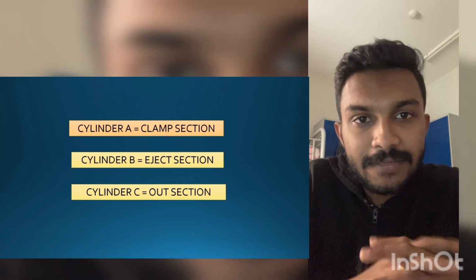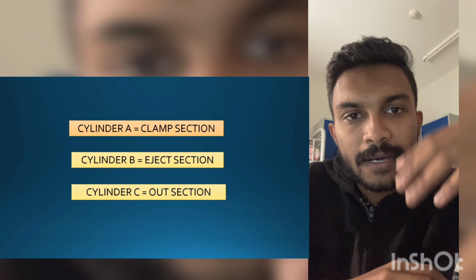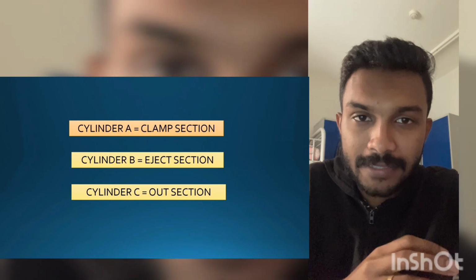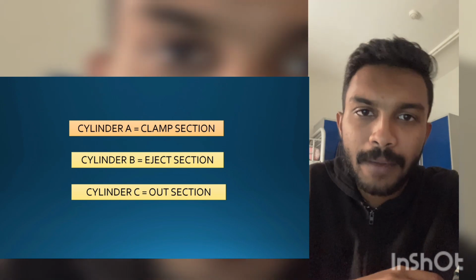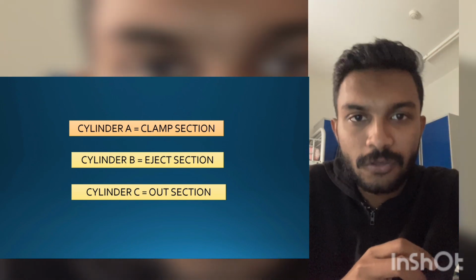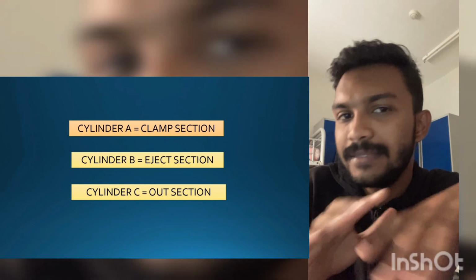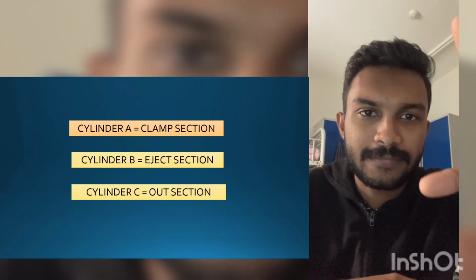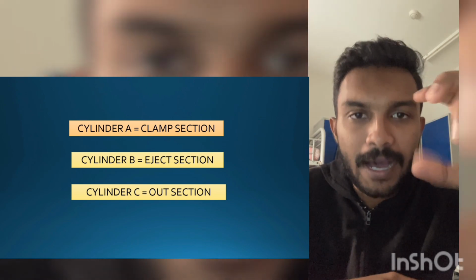Okay, cylinder C is the out section, the last section here. Cylinder C will push the canned sardines or any items from cylinder B into the basket, which is clamped by cylinder A. After this process, another person working there will take the container back. Until then, no human does anything from A to Z. They just help and make sure those cans are the ones that need to go into the basket.